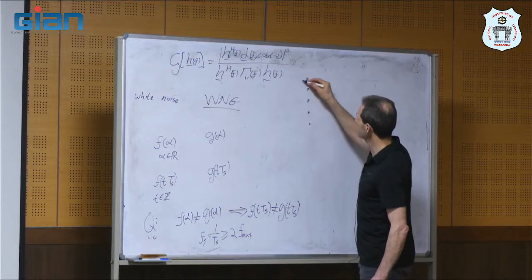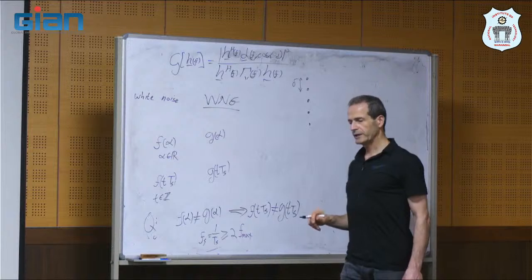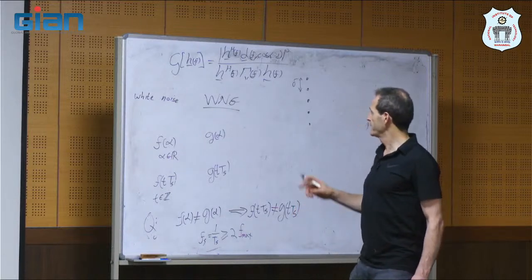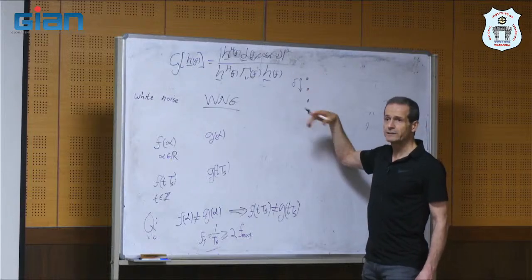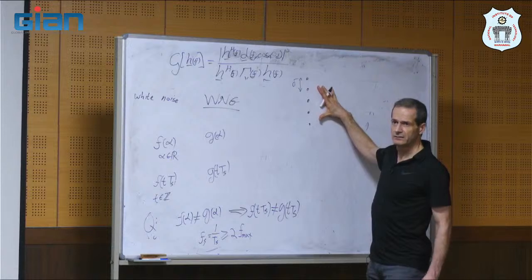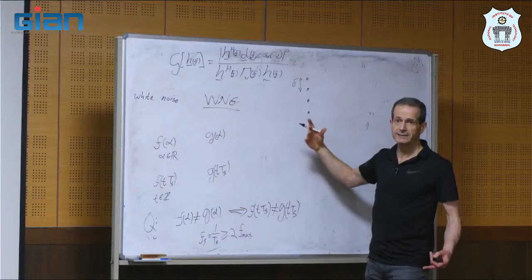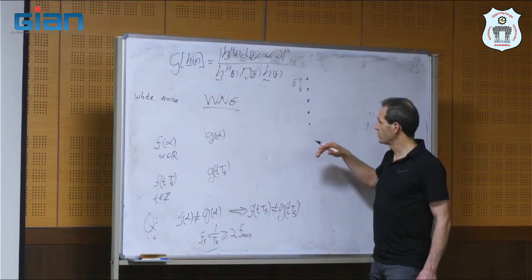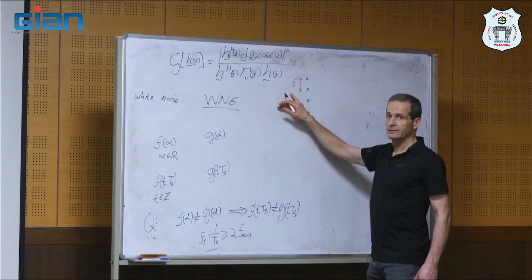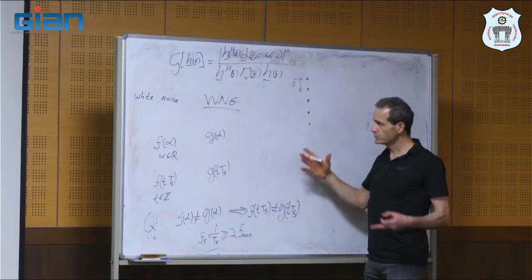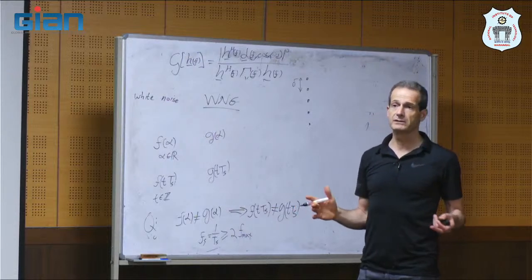This is a uniform linear array, and the spacing between two sensors is delta. So the question is, you see, if delta is small, then we don't have aliasing. So we ask ourselves, what is the maximum of delta? If we increase delta, maybe we will have aliasing. So what is the maximum possible delta such that any two signals that come from different directions will be different?